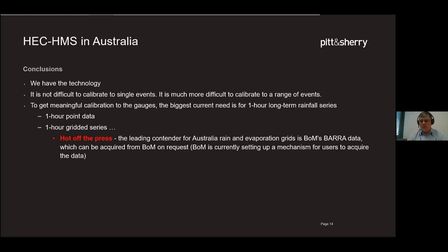Now, I've also, since doing that previous work in the Pilbara, been talking to the Bureau of Meteorology, and they are in the process of publishing the Barra grids, which will be available on request to users. Those grids are 1 hour rainfall grids, and there's also other climate data in there. I think that's a really major step forward because it gives you a single point of reference to get stuff from that you can use for the whole of Australia.